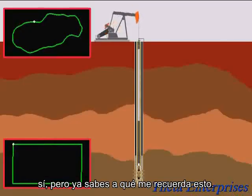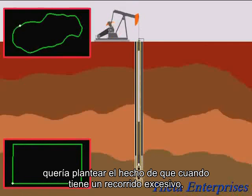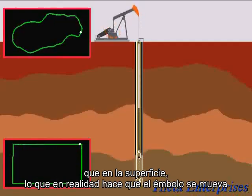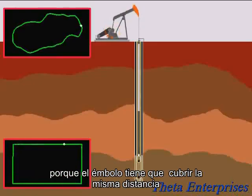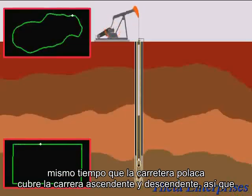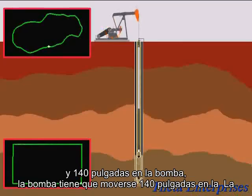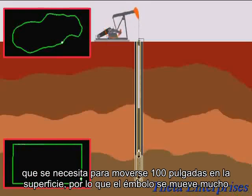Yeah, but what this reminds me of with your question is, I wanted to bring up the fact that when you have over travel, which in the traditional definition means you have a longer stroke at the pump than you have at the surface, that actually makes the plunger move faster, because the plunger has to cover the longer distance in the same time that the polish rod covers the upstroke and downstroke. So if you have 100 inches at the surface and 140 inches at the pump, it has to move 140 inches in the same amount of time that it takes to move 100 inches at the surface. So the plunger is moving a lot faster.